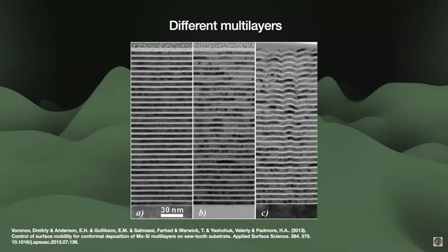At higher temperatures, the silicon and molybdenum diffuse into each other, forming a middle layer made from a silicide compound of the two. This silicide material absorbs UV radiation, so we will always fall short of the ultimate theoretical limit. At the very bottom of the mirror, there is the substrate.